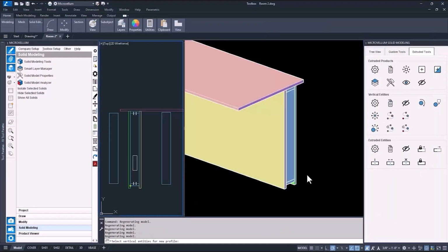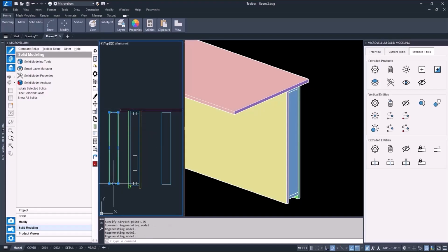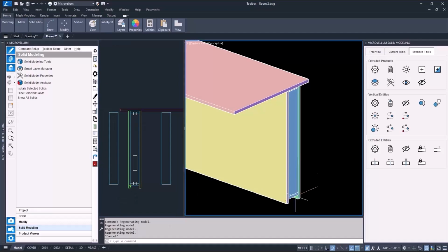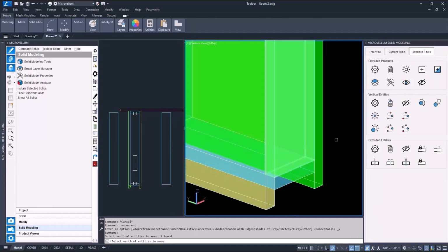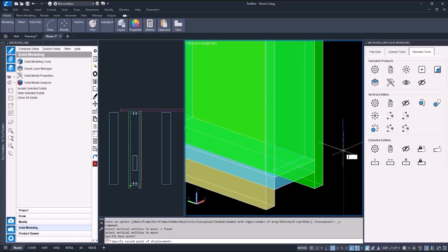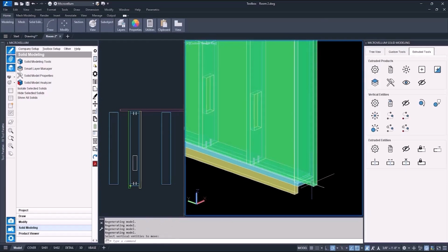Okay, good. But before I move on, I do want to make sure that this end stud profile is going to get dadoed into the top and bottom plate. So I'll just need to adjust the alternate profile size and extend it 1/4 inch in both directions. And if you're not getting the dado in the bottom plate, then go ahead and use that move command and move it down in the Z direction 1/4 inch. And this usually happens just because it's an alternate profile.